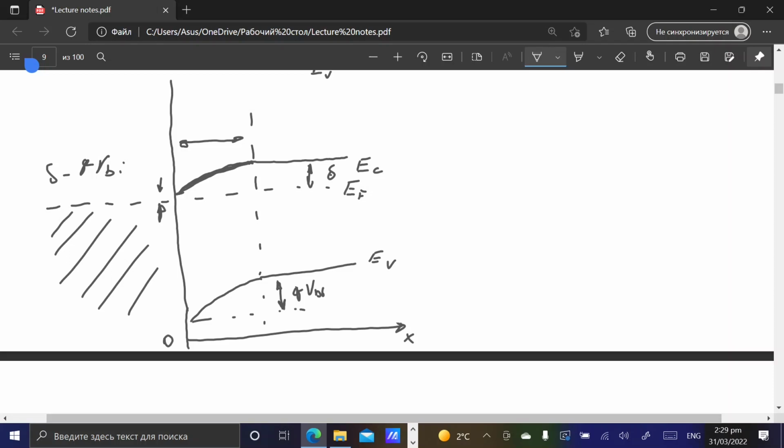So that is in line with the equation for equilibrium charge carrier concentration, and also in line with our discussion that work function is larger of semiconductor. That's why net flux of electrons will go from the metal to the semiconductor, means we will gain some electrons from metal in our semiconductor. So there will be more electrons in the region next to the interface between metal and semiconductor.